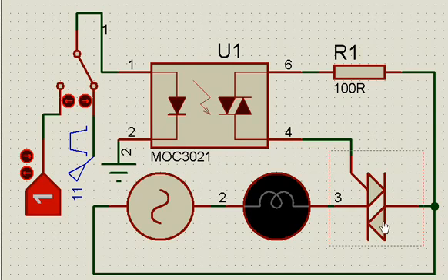It's not that we need any other source. Compared to the pulse transformer concept, this is a better solution because this is an optical isolation as compared to the pulse transformer isolation. You can see this DC side is completely isolated, and this AC side is completely isolated, and that is how this gives the best advantage as far as using an opto isolator for such a situation.